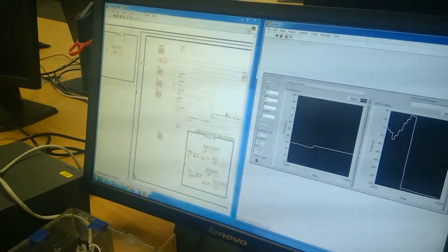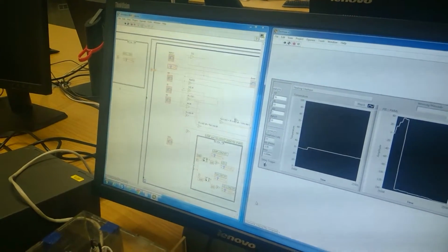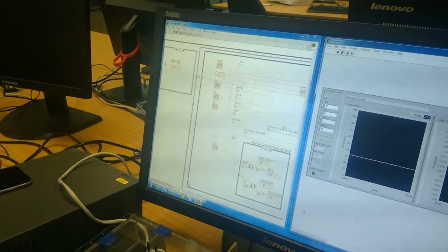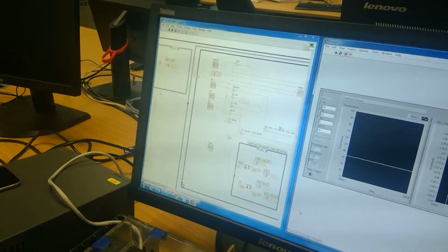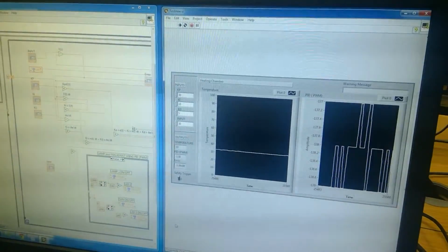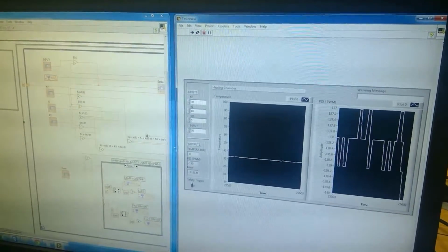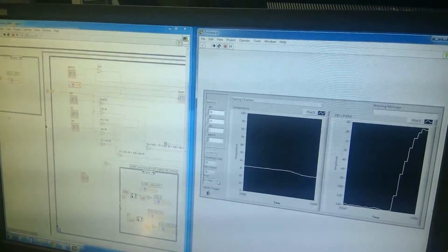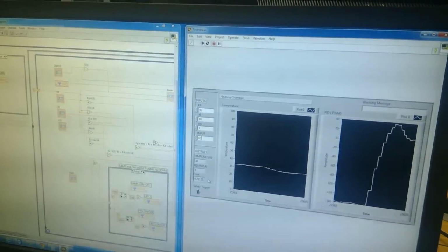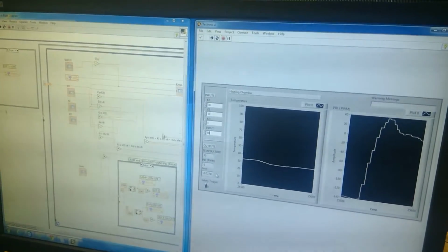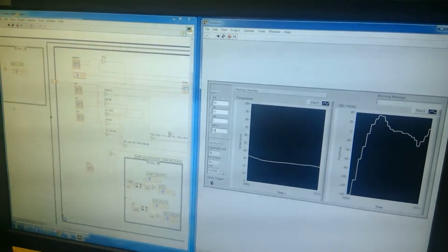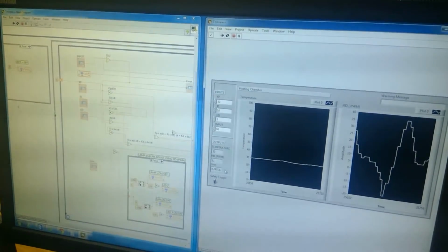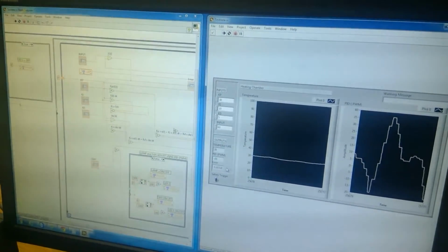And finally, in the specification of the coursework, our system has been specified not to ever exceed 55 degrees Celsius. So to show that the system will not exceed 55 degrees, let's set the system to about 60. Setting this, we'll be expecting that the temperature will never reach 60, because as soon as it gets to 55, the lamp from the system will switch off.